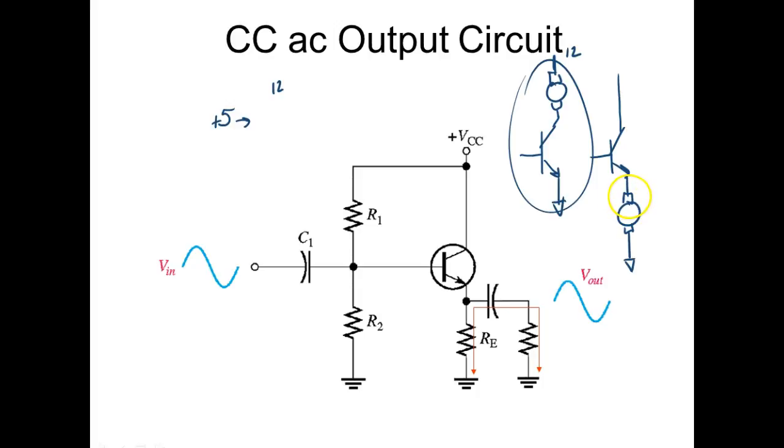If the voltage was going to be the same, so if I was in a digital circuit running a 5 volt motor, then odds are we would run it down here. Makes sense? So if your voltage doesn't change, we'd run it in the emitter. If it does change, we'll run it on the collector.